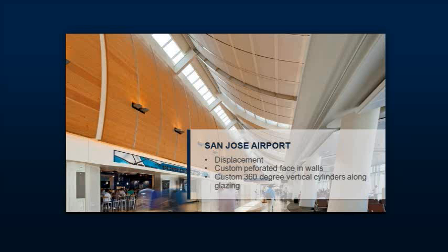Again, in San Francisco, this music conservatory uses displacement ventilation. Now, if you want to talk about a space that has some challenging acoustical requirements, it's one of these types of spaces. Anywhere I have fine art presentations ongoing, I always start with displacement because I can meet NC10 in these spaces from a supplier point of view a lot more readily than I can with anything else. Also, because of the variance in occupancy, I can handle the loading far more effectively.